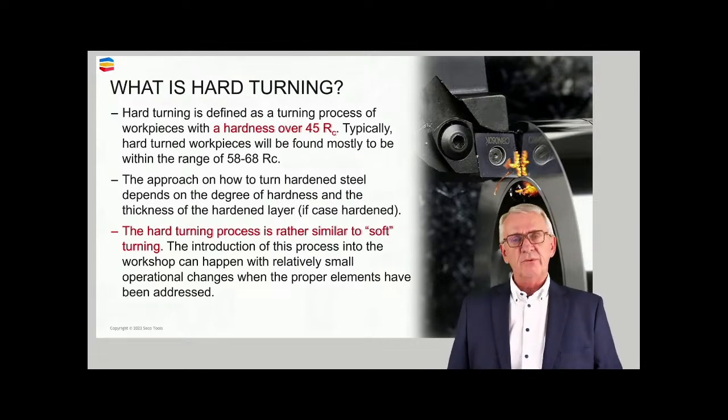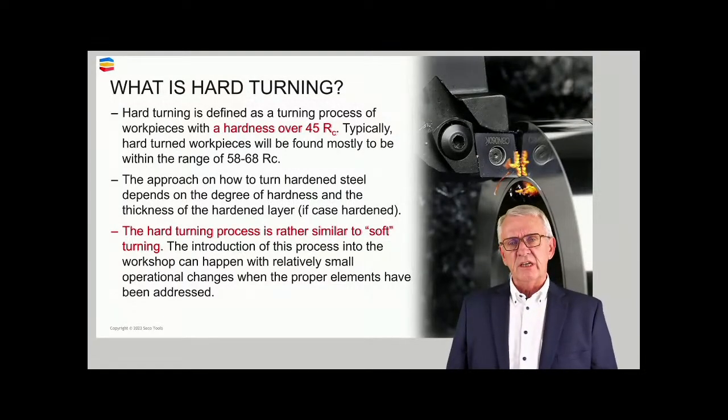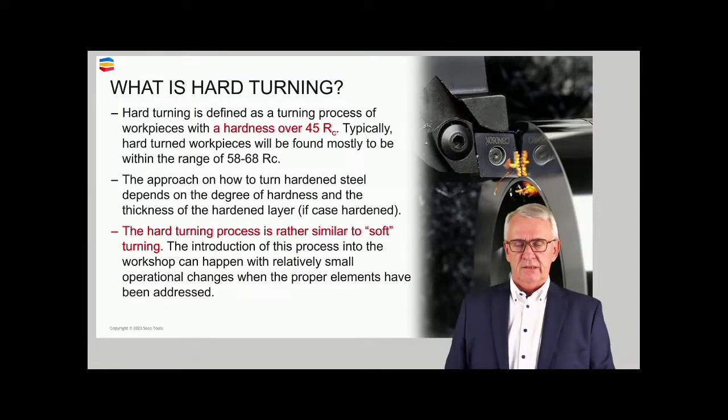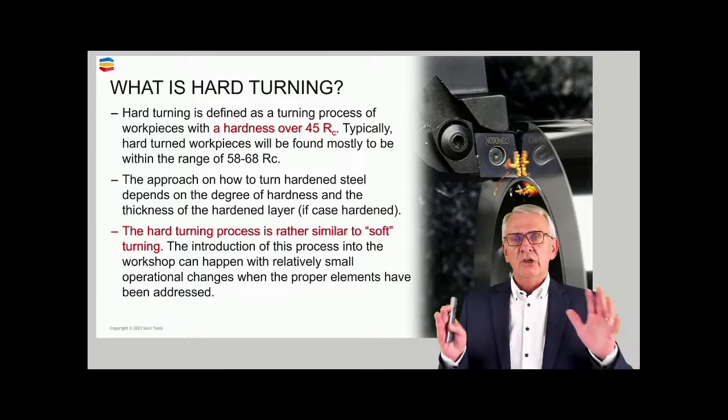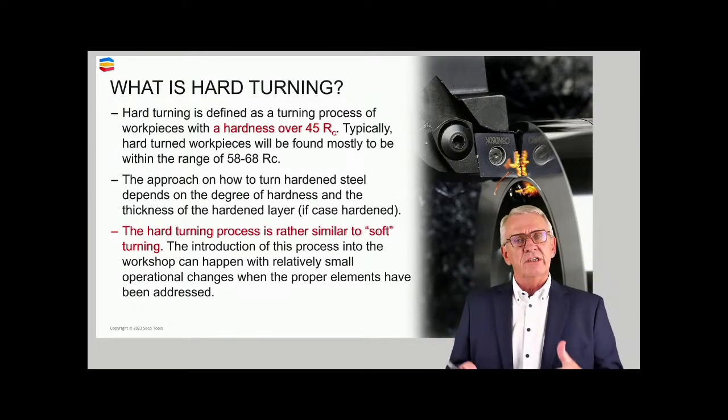Traditionally, we said in the past, there were two kinds of thresholds. One threshold was material hardness somewhere around 300 Brinell. We were then mainly thinking in terms of steels and cast irons, to some extent stainless steels, but we said when the hardness is below more or less 300 Brinell, we call that traditional machining. I on purpose do not use the words machining in softer materials because, what is softer? But 300 Brinell was kind of a borderline. Below 300 Brinell, it was kind of, don't worry, things are going fine. You don't have exceptional problems during machining. So it's a relaxed situation.